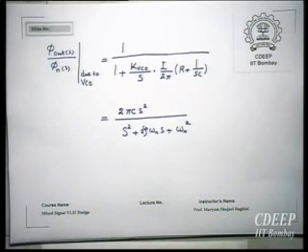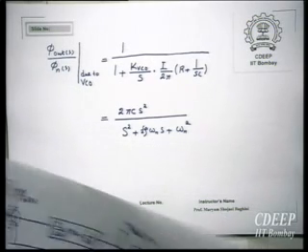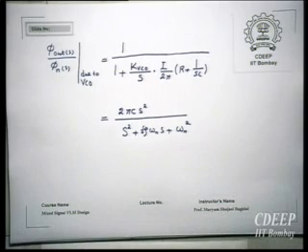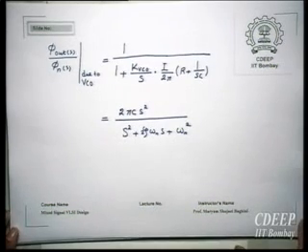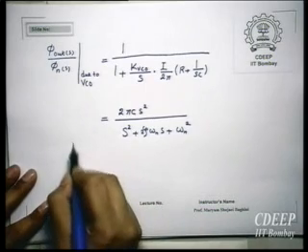Now it's very interesting. This is a high pass transfer function. What does it mean? If there is high frequency jitter in the VCO, it will actually come to the output. Therefore, the PLL VCO should be designed with low phase noise or low jitter, because the PLL is not able to reject that. In contrast, the PLL is able to reject low frequency jitter of the VCO. That's a very interesting behavior.